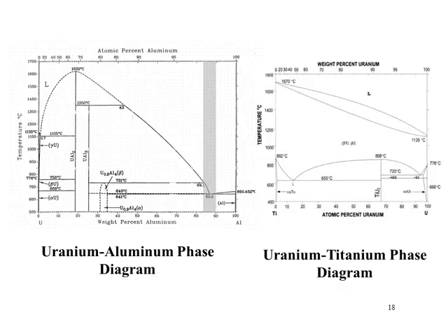Here is an example of two phase diagrams. We see the uranium and aluminum phase diagram. This is the liquidus phase. Here's uranium, here's aluminum, here's 100% uranium, and these are the different phases. So if we start having mixtures, we'll form two phases here, one being the uranium metal and one being this intermetallic uranium aluminum 2.